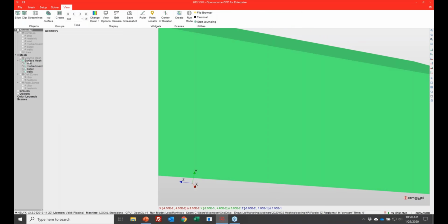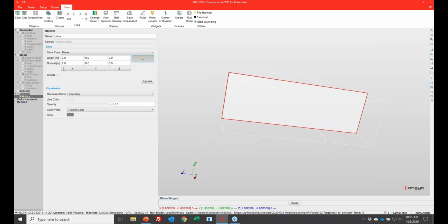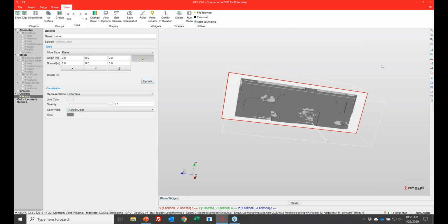Let's go to the View tab, and let me take a slice, and let's do a slice through the volume mesh, and let's not decompose the polyhedra. The way that the visualization works is it takes every cell, and if we want, it'll decompose it into tetrahedra. I want to see the actual shape of the cells themselves. So let me hide that. Let's do it in the X direction. And let's do a crinkle cut because I want to see what those cells are shaped like.